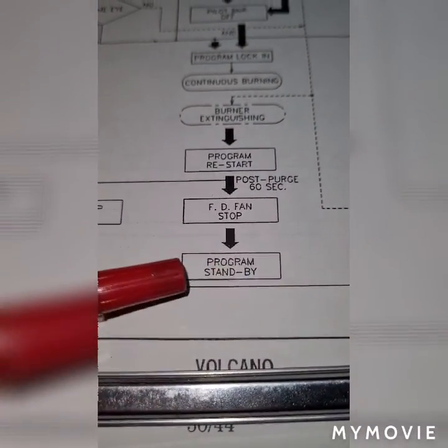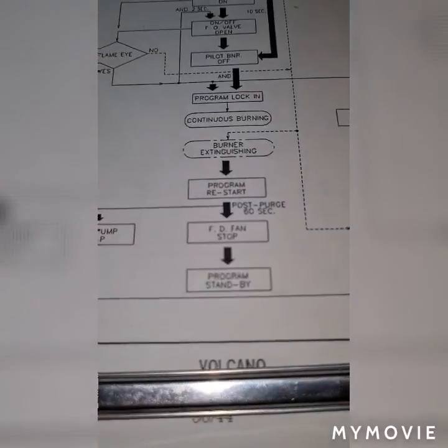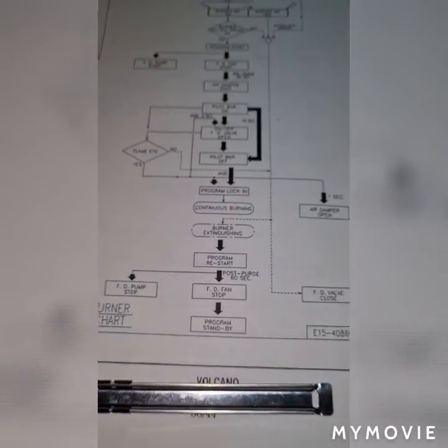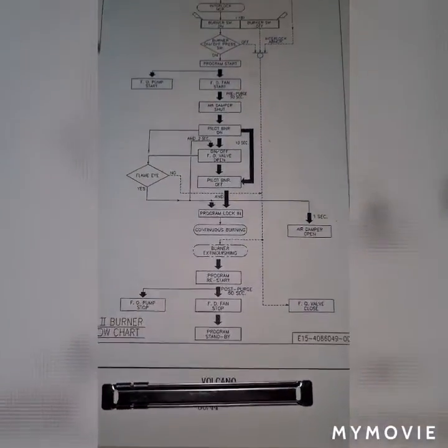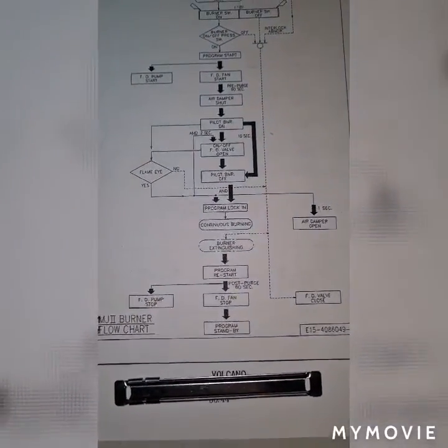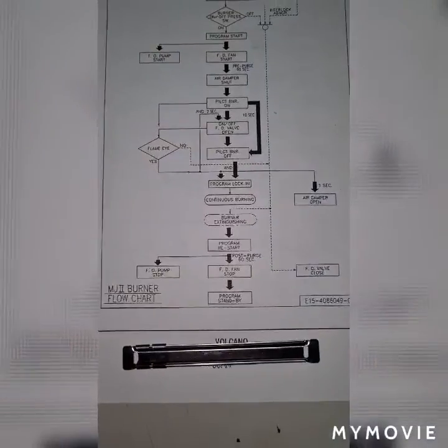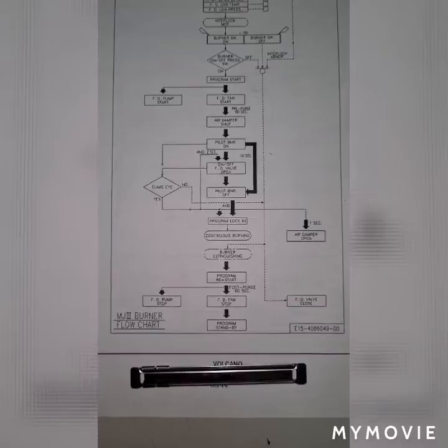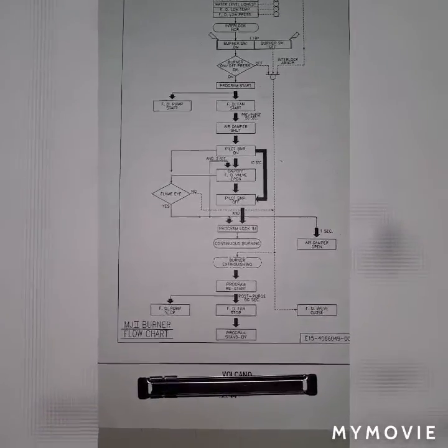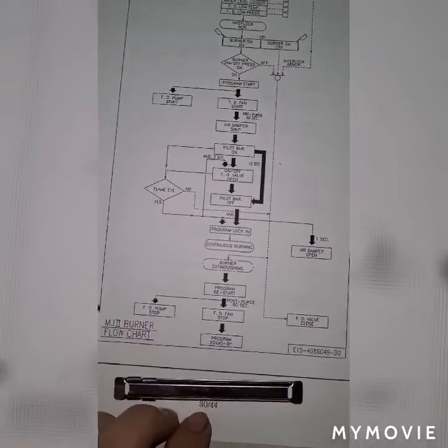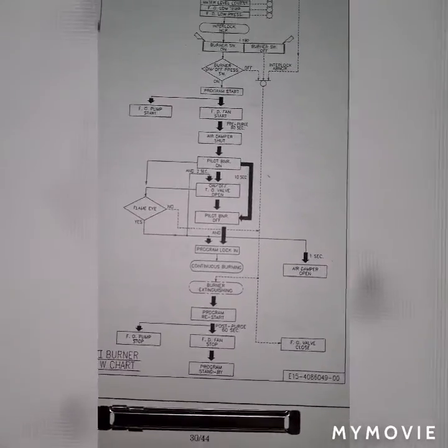This standby mode lasts until the steam pressure again drops from 0.62 megapascal lower to 0.47 megapascal. My steam pressure switch and pressure transmitter control and monitor the pressure. When it drops to about 0.47 megapascal, the pressure switch gives a signal.